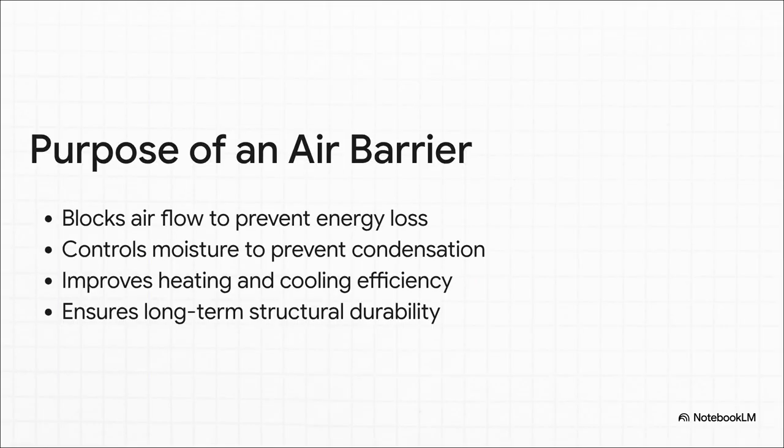Now, what's so cool about this is how this one single function does so many things. By stopping air, you stop energy loss. And by stopping that warm, moist indoor air from hitting a cold surface, you prevent condensation. This, of course, makes your heating and cooling systems way more efficient, and it protects the whole structure from moisture damage down the road. For the PPD exam, you have to remember it's about both energy and durability.